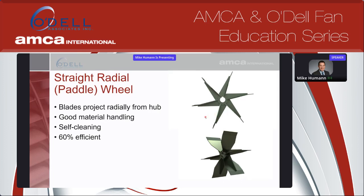Efficiencies tend to be about 60%. Sometimes you can get a little bit better than that if you make a really good selection, but they're not efficient fans. They tend to be noisy. So that's something to take into consideration when you do need a straight radial wheel like this.